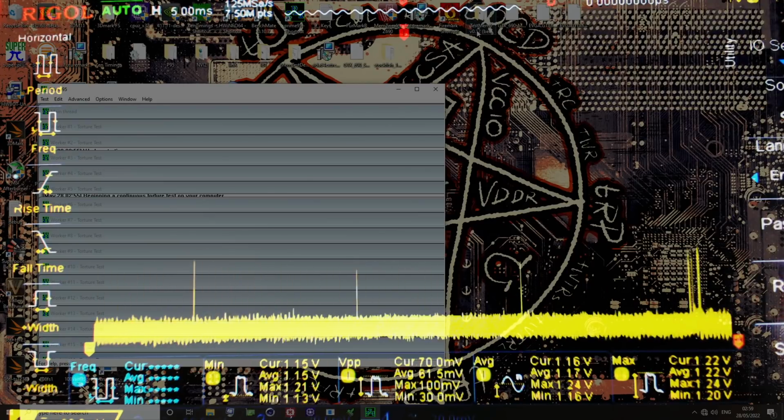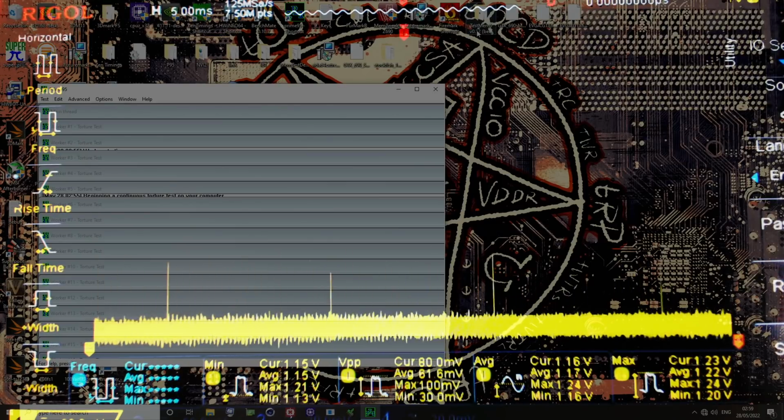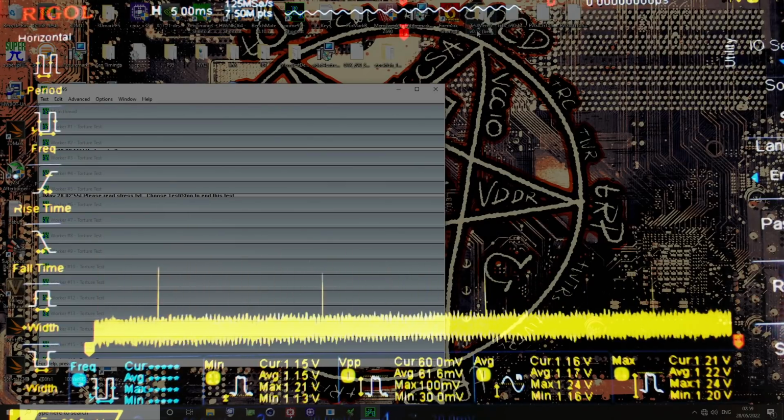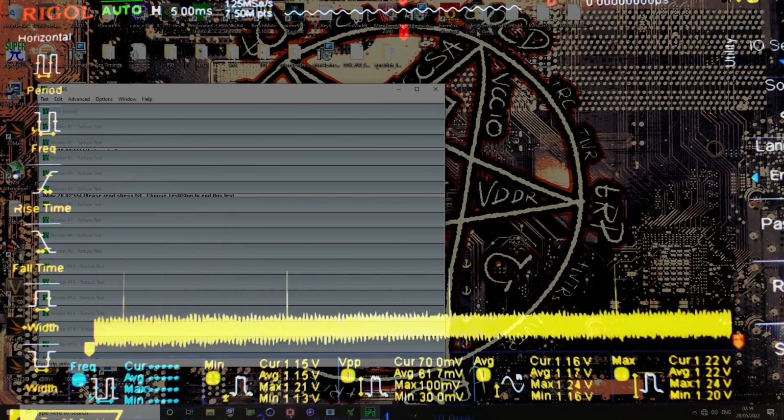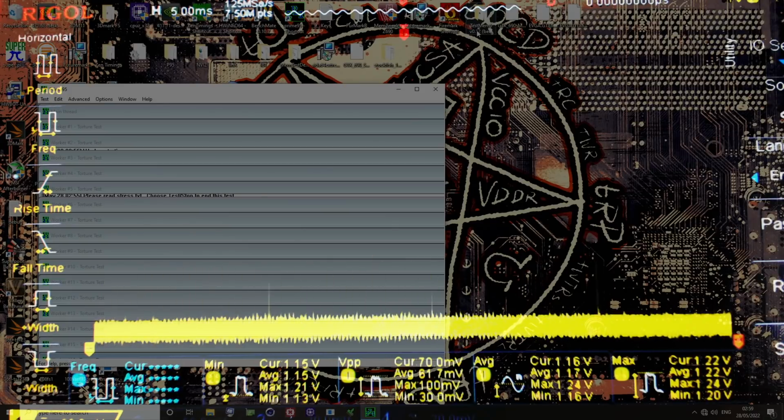But the Super I/O being connected to the Vdd sense is skewing the voltage reading, which is bad. The whole reason we have a dedicated Vdd sense connection is so that it's immune to outside influences as much as possible. And then you have this happening.